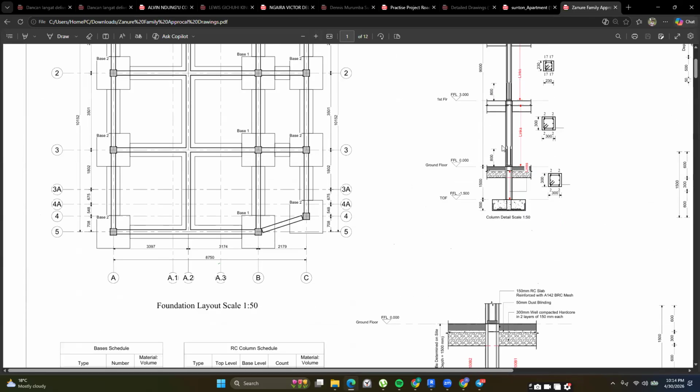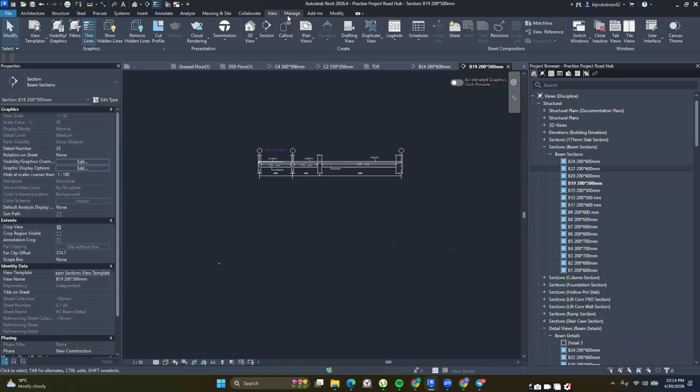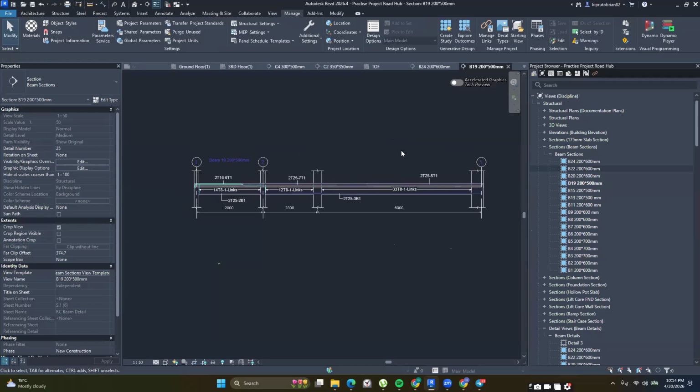All right. So to change how your rebar appears, to change the color of your rebar, you're going to go to manage. Okay. And here you can basically change the appearance of any object throughout the entire project. Okay. So this is the difference between the visibility graphics and the object styles. So visibility graphics is per view, and then from each view, you create a view template. But for the object styles, for select items, you can change how they appear throughout the entire project.